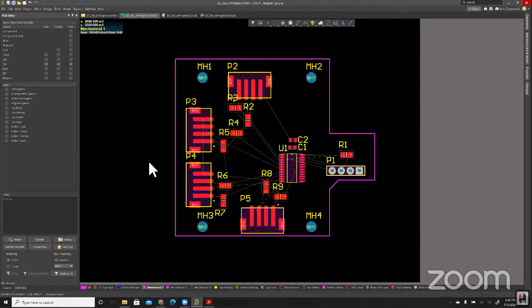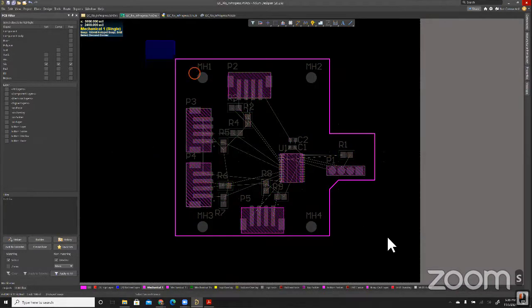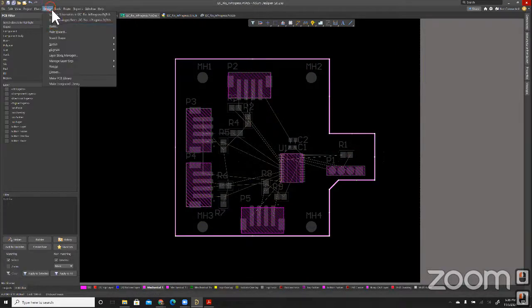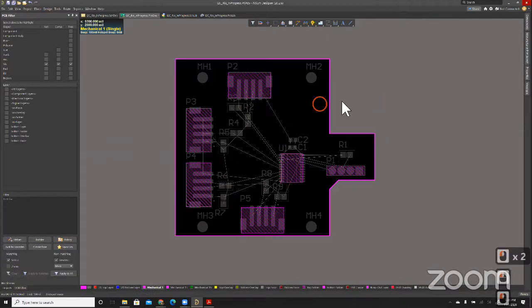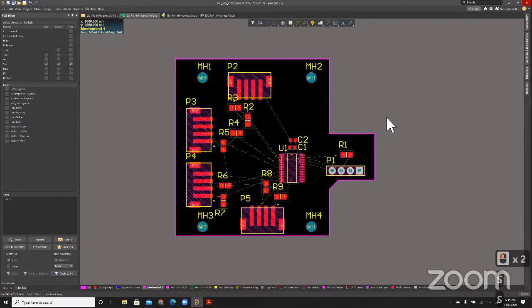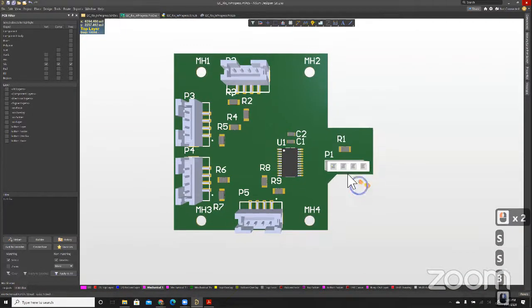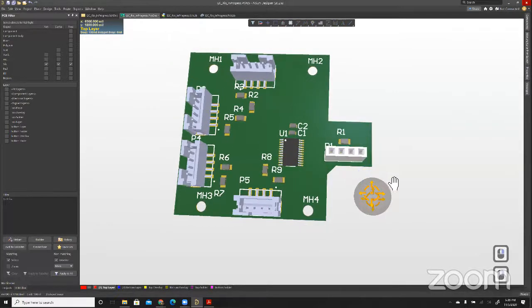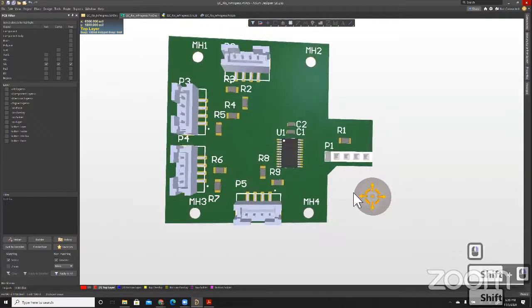So I'm going to make it so that only mechanical layer 1 is showing, by hitting Shift S, and then I select those components and I go Design, Board Shape, Define from Selected Objects, and now the board looks like this. And so if we look at the 3D model, oh, whoops, I've got this on the wrong direction here still, but this gives you an idea of what the board would start to shape up looking like.